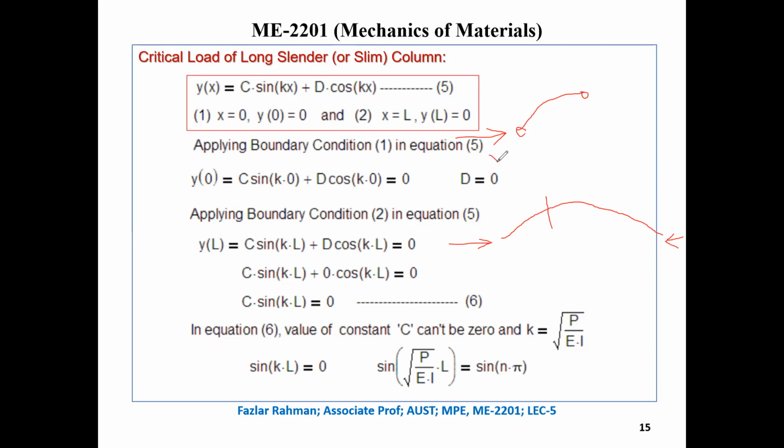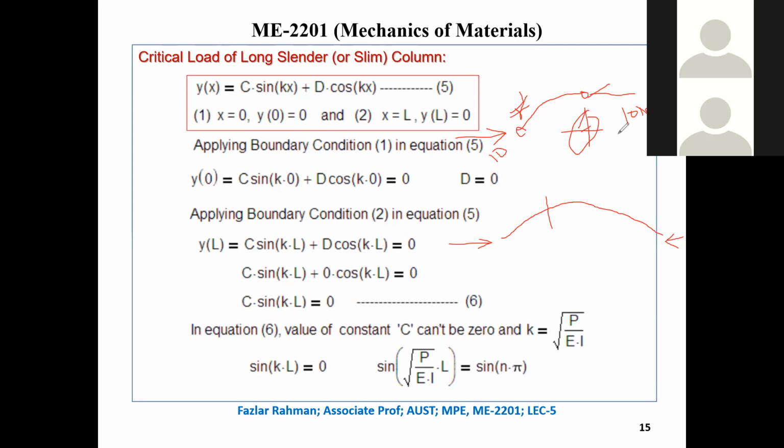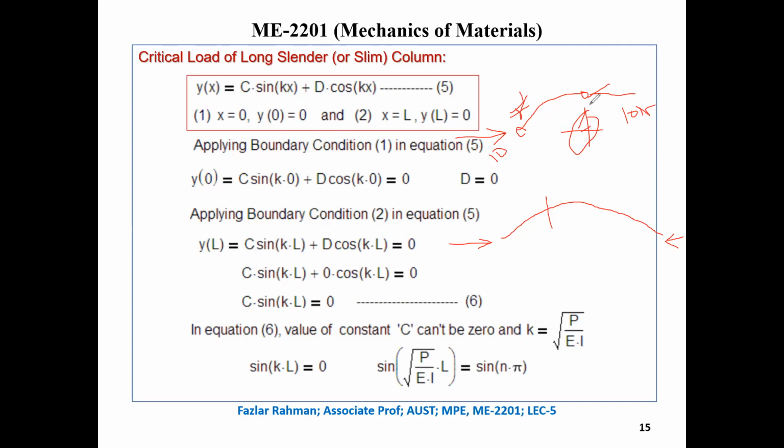So this is say 10 Newton. So obviously it has to be 10 Newton, right? And you see there is no other force. If there is a vertical force over here, then you can put say a vertical force working right over here downward, then over here will be upward. So if this force is working parallel to the surface, then there will be shear stress and shear force. But since we don't have this force, that means we have only normal force. And this force passing through a different point, that means we will have a moment.